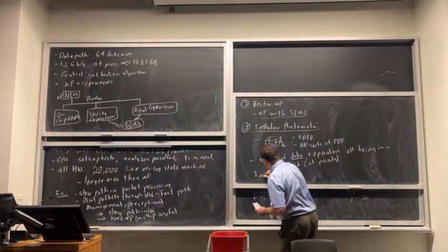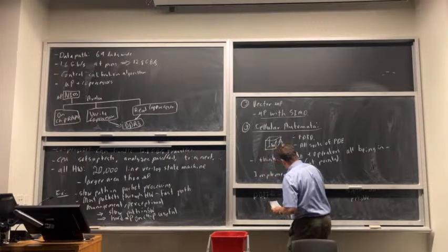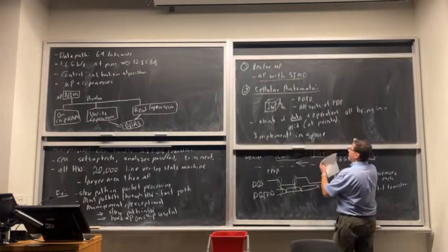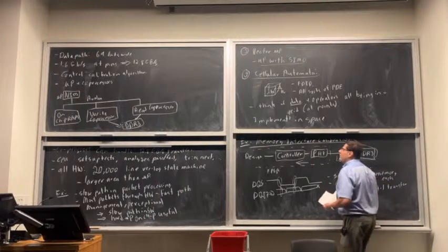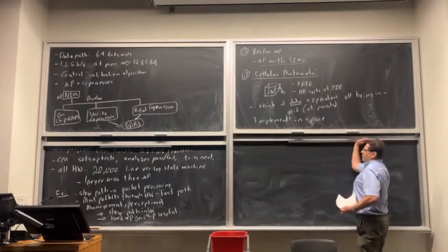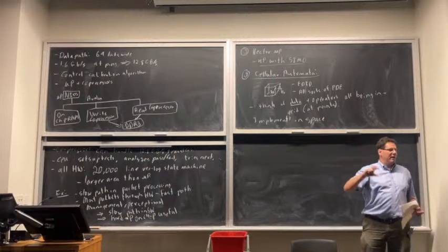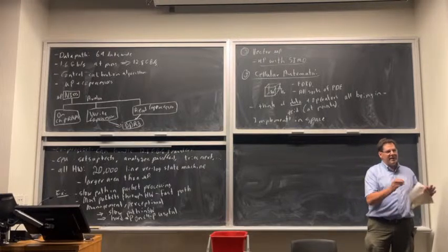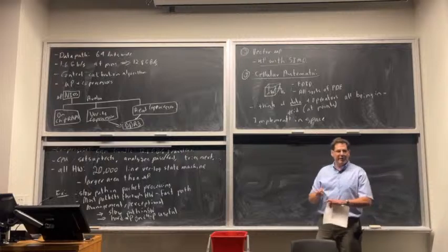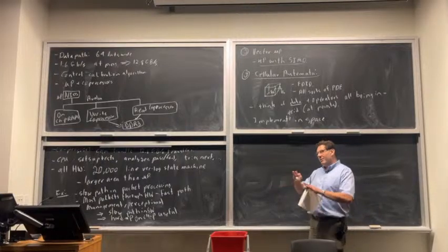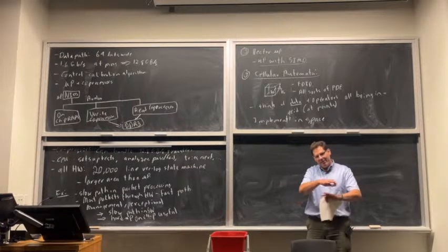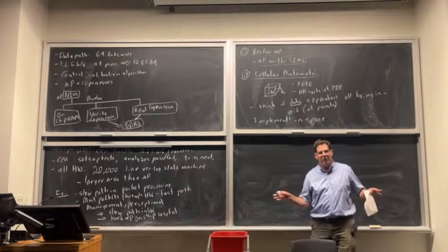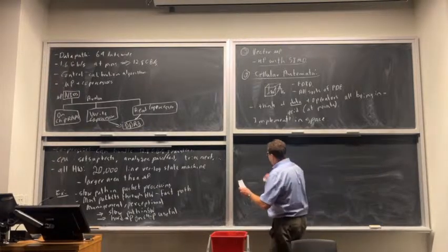Okay, so let's say we implement this in space. Implementing in space means we basically take every one of those grid points and say that certain logic elements in the FPGA are storing it and also producing the operators to update it. And we repeat that over the whole chip. If it's two-dimensional, it'll be really obvious how to map that. In 3D, it's not going to be a perfect mapping. We can still distribute it in space, but clearly we have to squish which grid points go where, so the communication won't be quite as local. But we could still have it work in space. So it's got a lot of nice features.